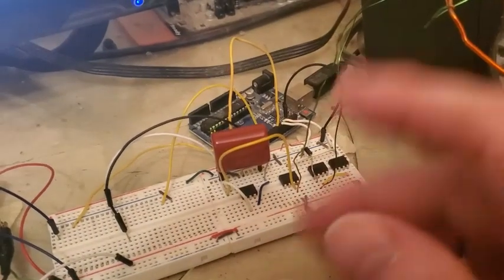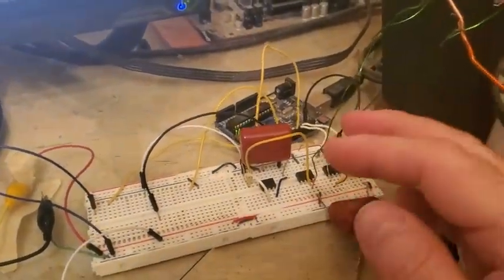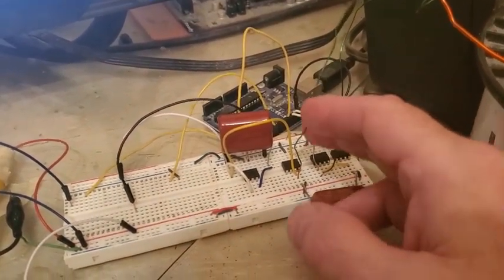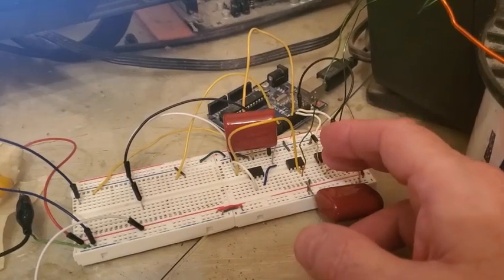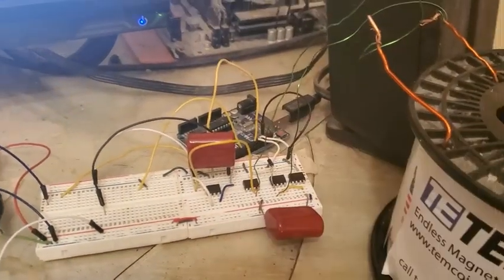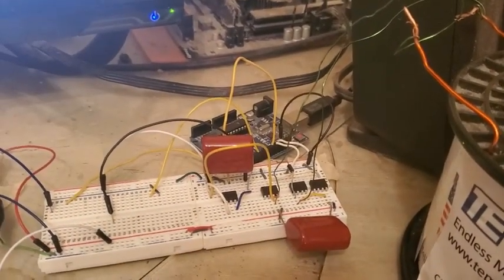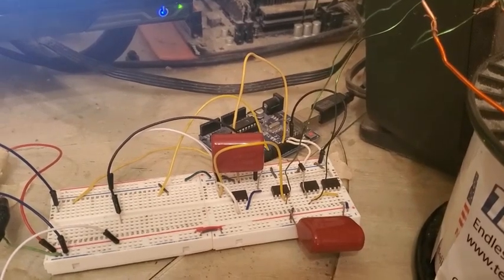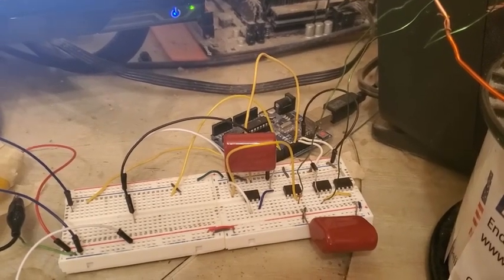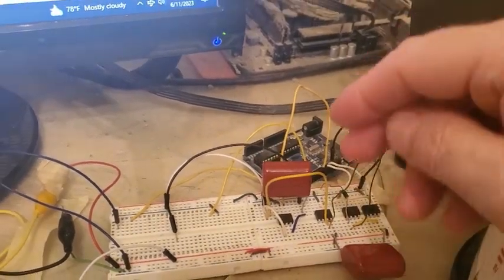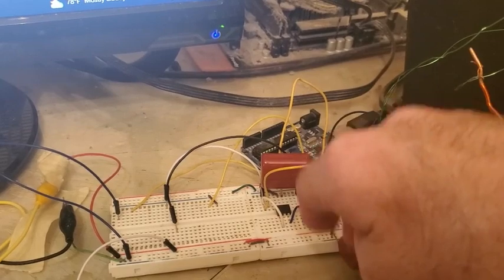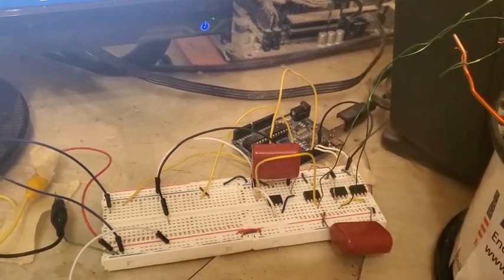And maybe I'm wrong on these things, but again, I'm going to be continuing to investigate. What are the things to do going forward? I think one of the main ones is to get a better switch, and ideally I will be able to opto-isolate a MOSFET. I know they have prepackaged gate drivers, but that's kind of overkill for what I'm trying to do, although at some point I should look into that. And if I can't opto-isolate a MOSFET, at least opto-isolate a BJT. If worse came to worse, just repeat the way John Bedini did it with the bipolar commutation circuit, because that also would be an avenue that should work.